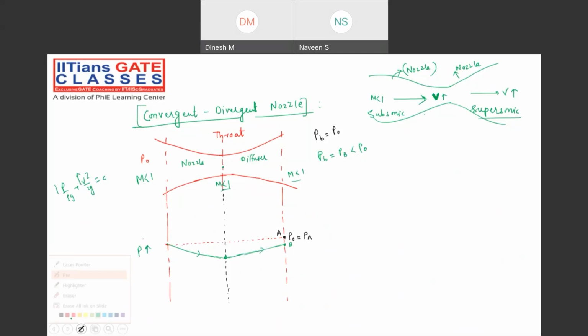Perfect. Now the next part: you further reduce the pressure to point C, like this and like this. That means we still have subsonic flow. But my dear friend, suppose you have reached the maximum condition. I'm taking the maximum condition to be C dash, which corresponds to the choking condition. Now you have reduced the back pressure to P star. I'm calling this PC dash.